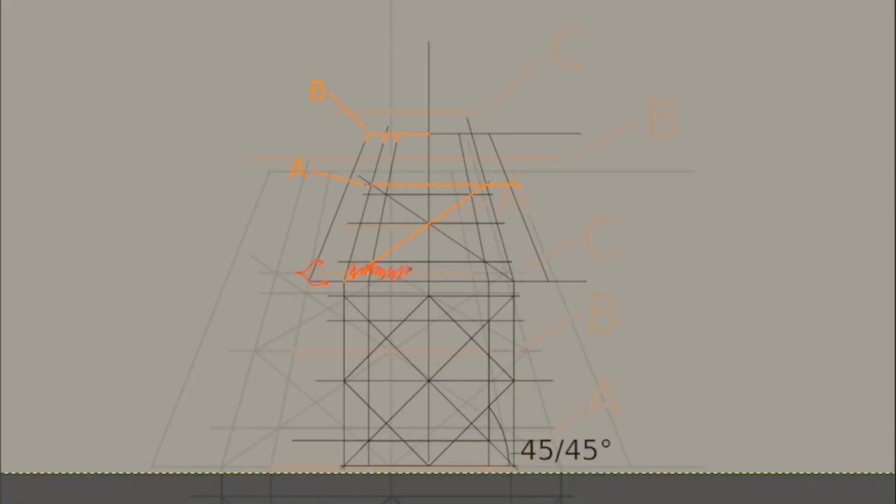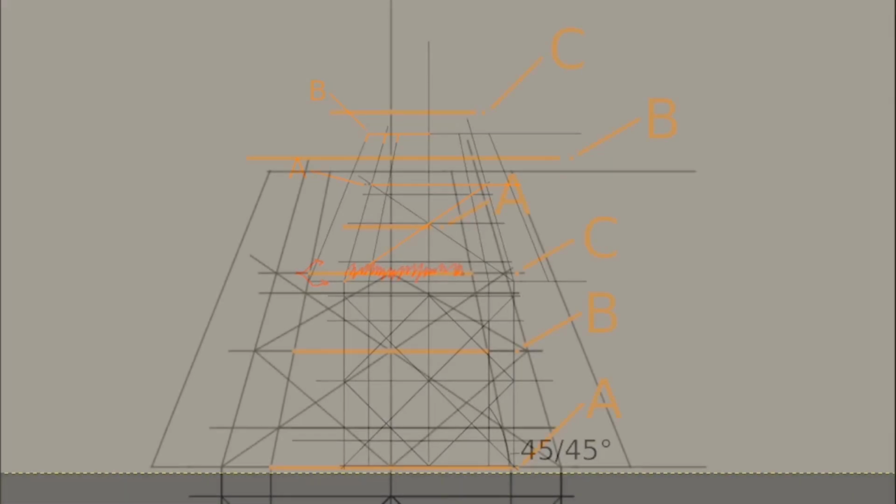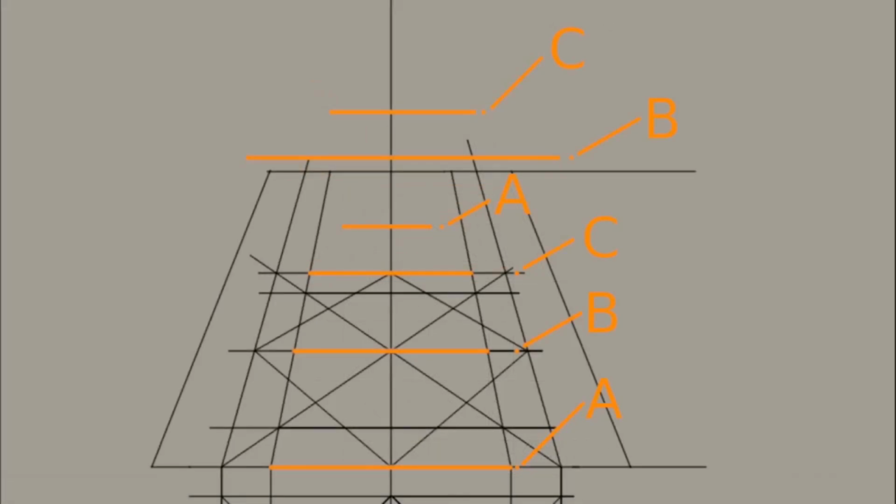Number 3. The height of the rotated cube. Mark the heights of legs or corners on the bottom plane. Measure the width of the unrotated square in perspective that is directly aligned horizontally with the corners of the rotated square in perspective. These are the heights of the corresponding legs and are drawn on the corners of the rotated square that's in perspective. The heights can be measured, then those measurements can be replicated at 90 degrees to get the height, or a line can be drawn to the length of the reference line and then be rotated and placed. The important part here is that the height lines be taken from the width of the unrotated square.